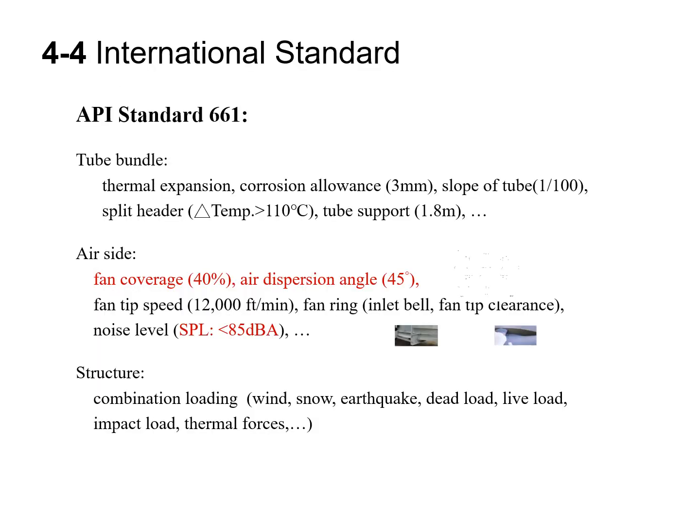API Standard 661 applies to horizontal type air-cooled heat exchangers, but can also be adapted for other configurations. It specifies design, material, fabrication, inspection, testing, and shipping requirements for such heat exchangers. Here are key design considerations covering the tube bundle, airside conditions, and structural aspects.